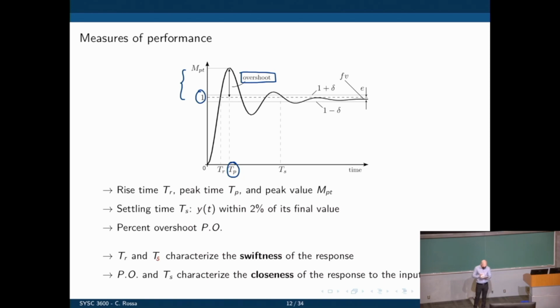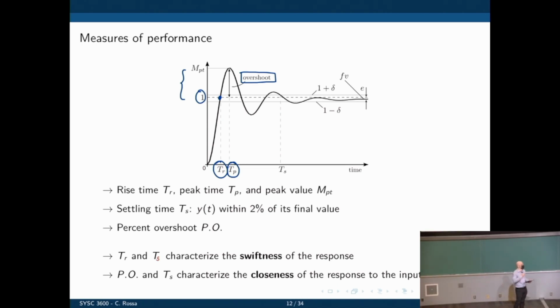We also have what we call the rise time, which is TR, is how much time the system takes to first cross the steady state value, which is seldom used in most control systems applications, but in certain applications this is useful, especially if you have wind tunnels or a room with temperature control. We probably want to know how much time it will take to first reach the temperature we want, even though it oscillates a little bit later before it settles.